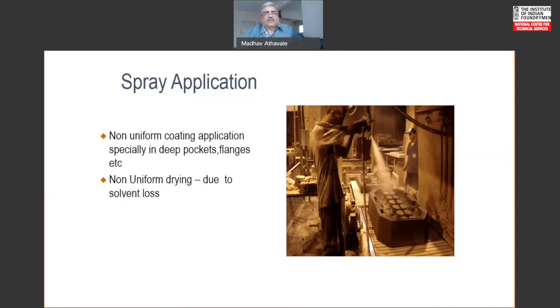It also may mean non-uniform drying due to solvent loss. We saw him flaming it off immediately, but sometimes if there is a delay, if the workers are not well trained, then in the spray the solvent goes away, and if you don't flame it off in time, then you will get non-uniform drying.